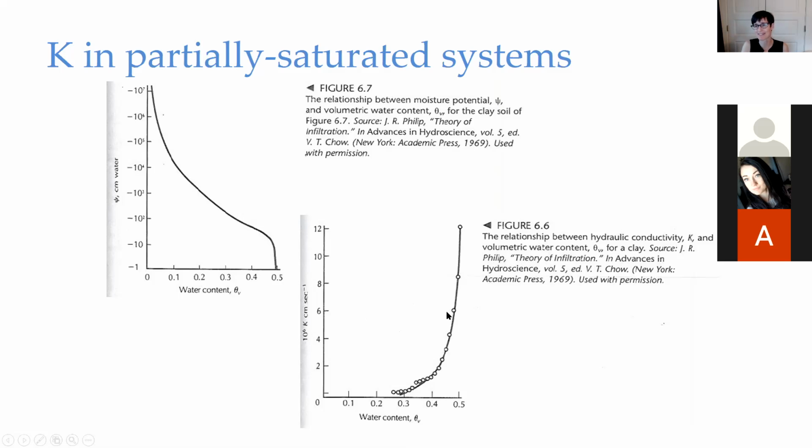The water can't flow as easily. There's air in the way. So it comes down and it declines like that. If you can write a curve that describes that kind of thing, you can also write a curve that describes this kind of thing. That's how you deal with those two terms that are nonlinear in the unsaturated groundwater flow equation.